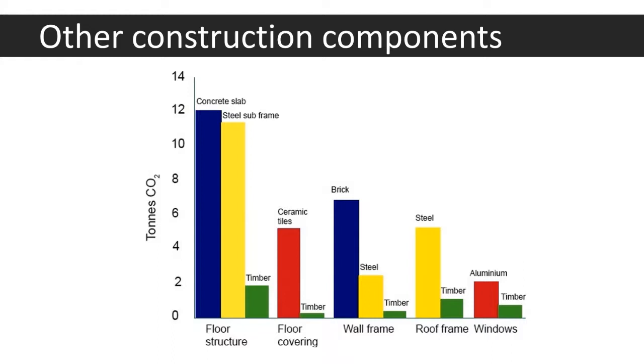Now, the thing is that this is not the whole equation. When we're looking at buildings, we need to also look at the whole life of the building. And in some cases, timber buildings can also result in some additional energy use, because timber doesn't have any thermal mass, so it doesn't allow the use of some passive design techniques. But this is another lecture.